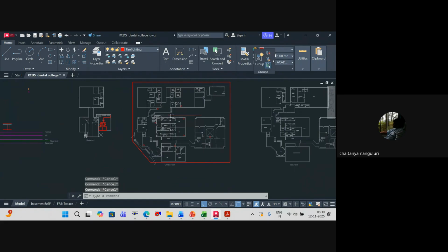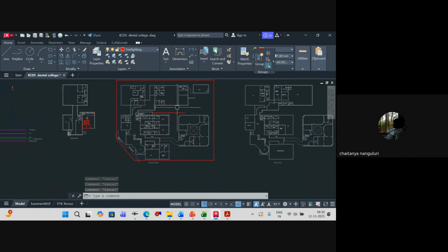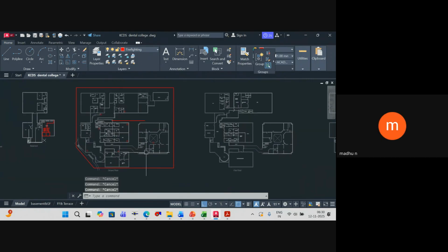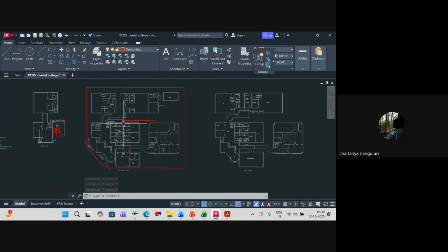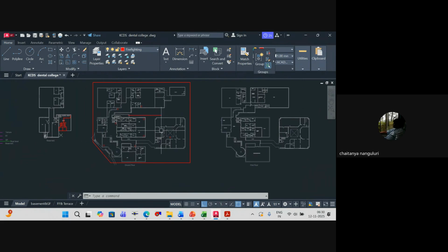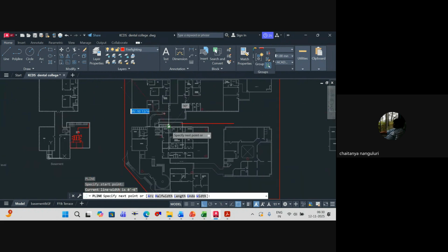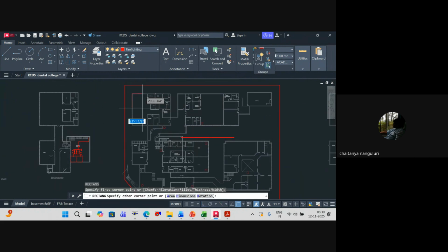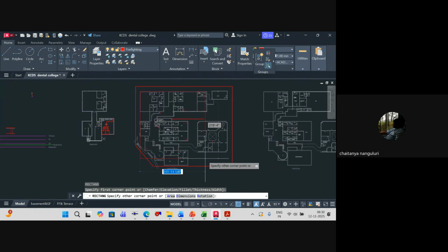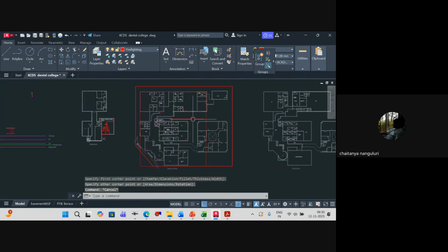Now, I have to have 2 or 3 different zones in this case, right? Because each zone of the sprinkler system cannot serve more than how much area? Not more than 32,000 square feet, right? So if it is not more than 32,000 SFT, I have to take the total area and then divide it. So let's take the area approximately. I'm roughly doing it because it can vary too much. Let's take this area.